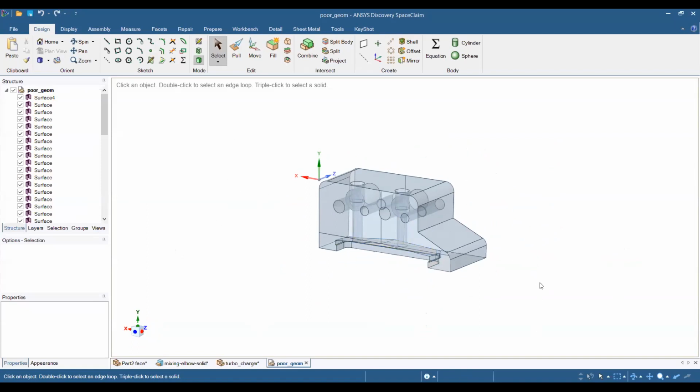These seem to be connected, but they're really not, because you have individual surfaces instead of condensing all of them into one single surface. Now, this is not suitable for extracting a flow volume. If I were to extract a flow volume out of this geometry, because the surfaces are not connected, my volume would leak and I would not be able to extract a region out of it. So what I need to do is fix it. How do I do that?